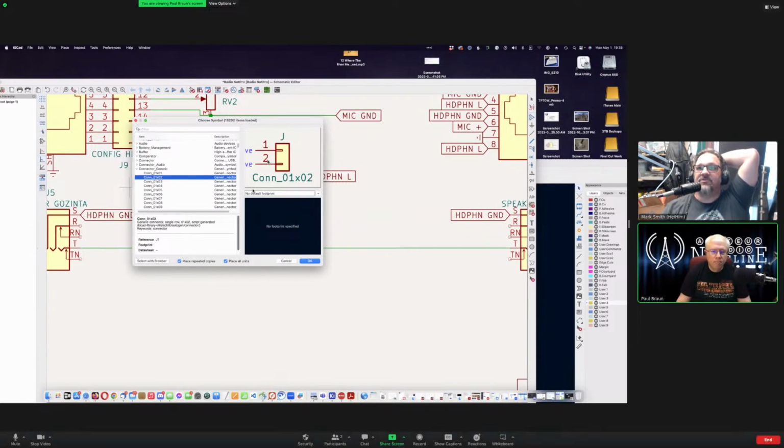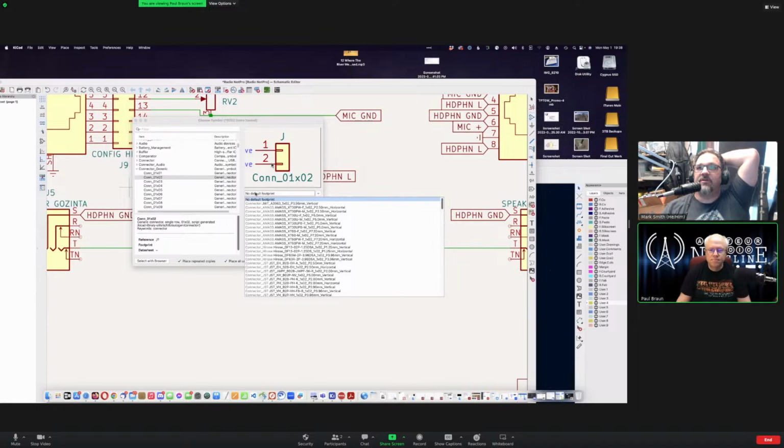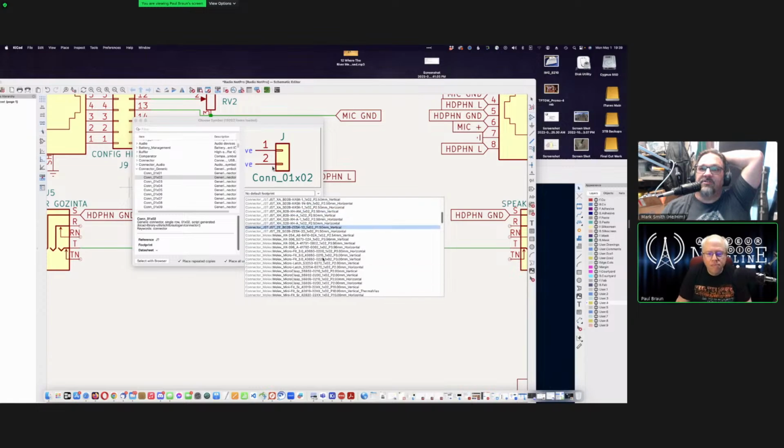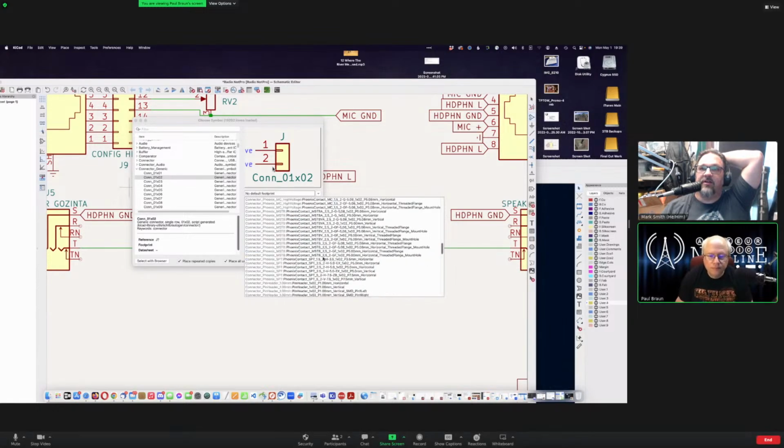Yeah, so see how those are numbered 1 and 2? Mm-hmm. Now, the unfortunate thing is that they both come out the same side of the schematic drawing, but I think that's okay. And then, yeah, you're just going to go down to pin header.